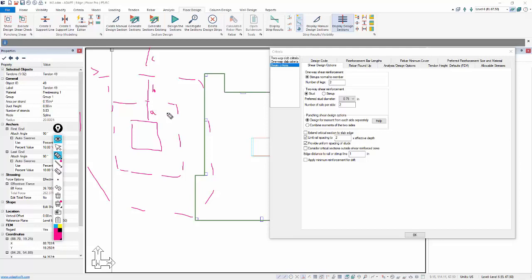You might need 2 studs at 3 inches here, maybe 4 studs at 1 inch here, 5 studs at 1 inch. So each one of these zones could technically have its own spacing and number of studs. This is based on, again, the calculation of required shear reinforcement within that layer, and that also is subject to minimum reinforcement requirements that are needed between each critical section.